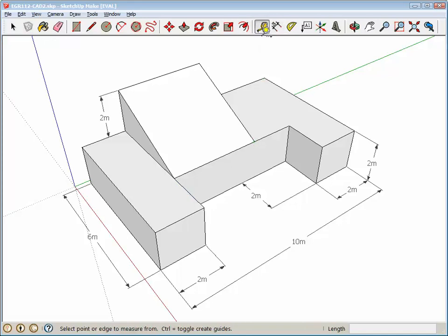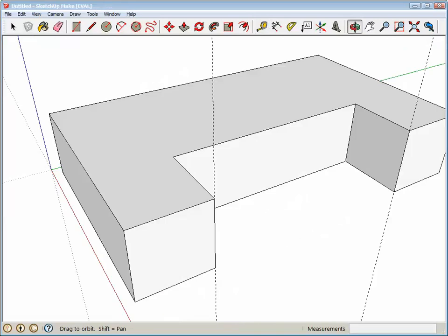What we can do is try to measure how far it is over like that. So I could use the measuring tool like so, and I can see down here on the lower right hand side when I reached my endpoint it was 4 meters. Alright, so going back over to that part, let's see what I can do here. How about I go 4 meters from this spot in like that, type in 4M, enter, and that's where it started right there.